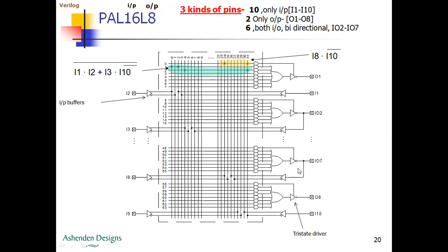So in the unprogrammed state, we have something called fuses, like these cross marks. What you're seeing here on the grid, we call the fuses. In the unprogrammed state, this X is present at each and every intersection of this grid.